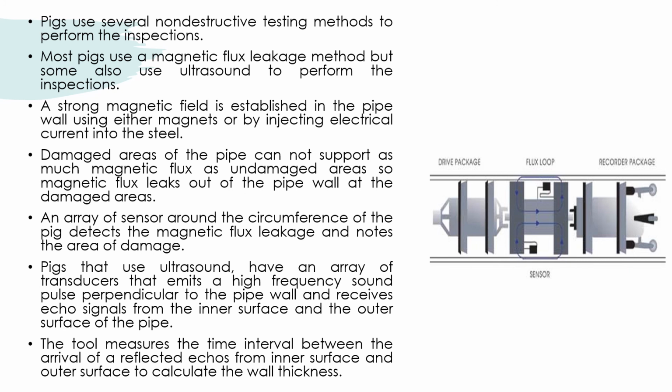The tool measures the time interval between the arrival of a reflected echo from the inner surface and outer surface to calculate the wall thickness.